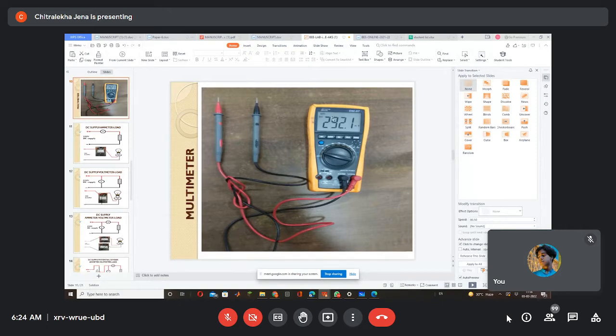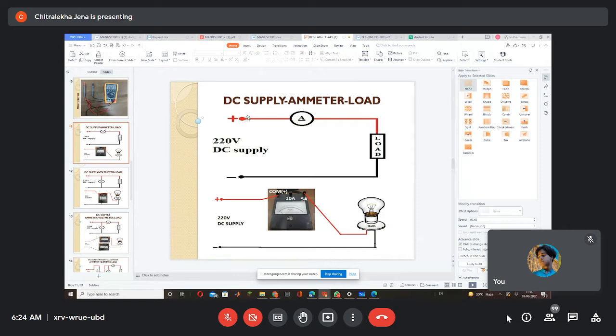Okay, whatever I have discussed, I have shown you in this connection diagram. Here this is an ammeter. I have told you 1 point is coming to the common, and this one, 5 ampere, is going to the bulb. So if you are connected in the 5 ampere range, whatever reading the ammeter shows you, you have to take the lower reading.